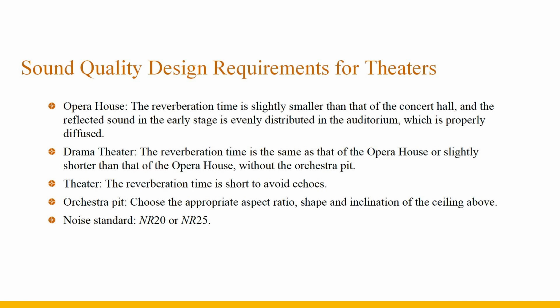The electroacoustic system should not only enhance the loudness of the auditorium, but also control its volume without destroying the natural sense of direction, so that the audience can hardly feel its presence. Audible noise standard is NR20 or NR25.